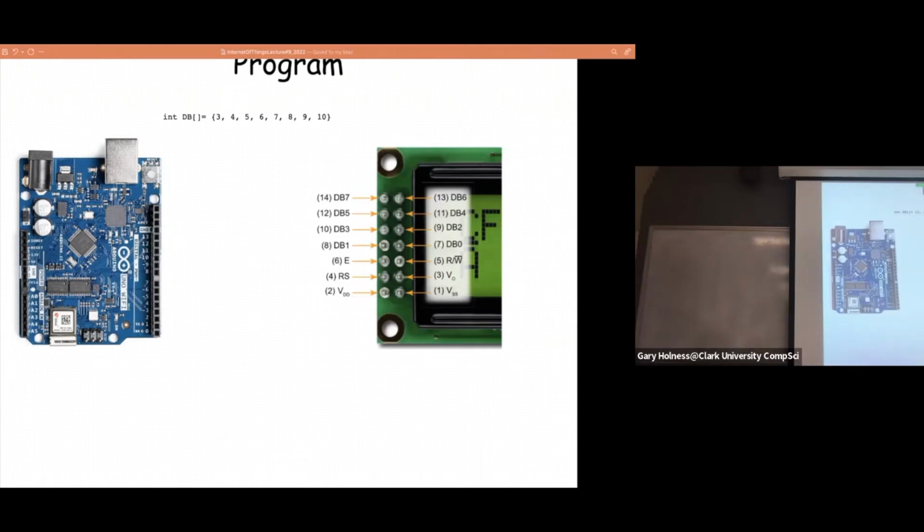And so here we have the pin numbers, and these pins, as described here, each column represents the odd number signal pins for the device, and this next column, the right-hand column, represents the even numbers. So we have the evens and the odds, and when we count them, we number them row major from right to left. So this is pin 1, 2, 3, 4, up to 14.